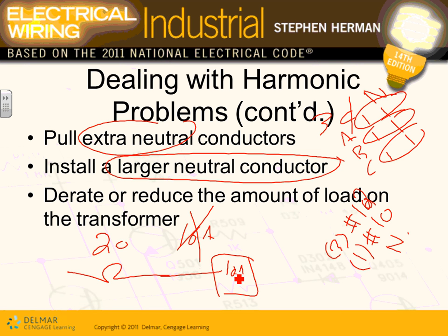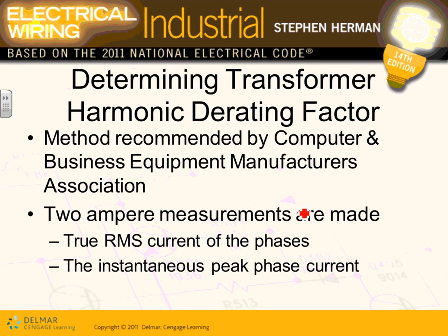It's my opinion, taking into consideration that a lot of engineering firms don't load the circuit beyond 70% instead of 80%, or 60% of the circuit. A lot of people say, okay, I'm not going to load my circuit beyond 70% of the rating instead of 80%, or 60%. That's very common. So they reduce the load on the circuit. Who cares? You add extra circuits to handle those triplens.